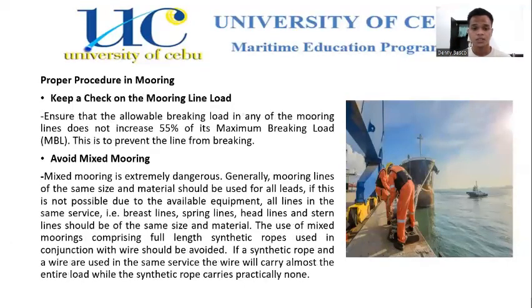Next is keep a check on the mooring line load. Ensure that the allowable load in any of the mooring lines does not exceed 55% of its maximum breaking load. This is to prevent the line from breaking. Next is avoid mixed mooring.